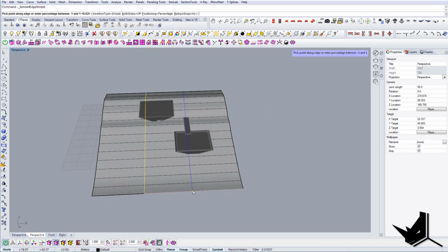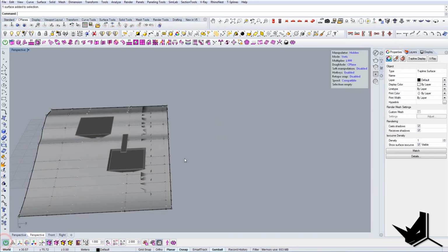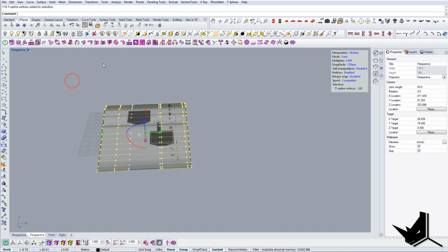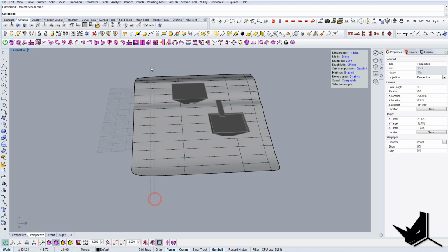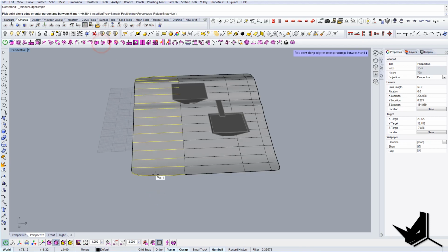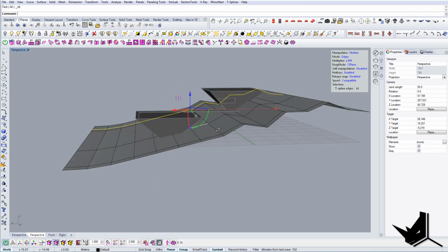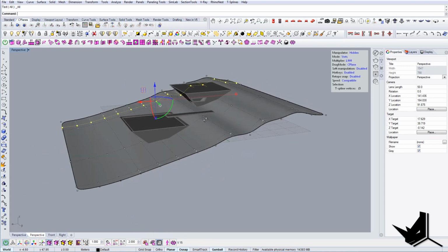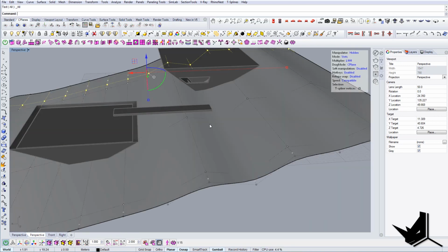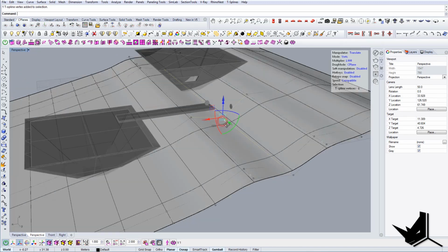edges here, so that I can have a better control of my T-splines. So of course I want to turn off the creases, so I want to remove them, and let's add another edge here, like so. This is the box mode, this is the soft mode. So right now I'm just going to play around here with my T-splines, and I'm going to try to get the best results here.